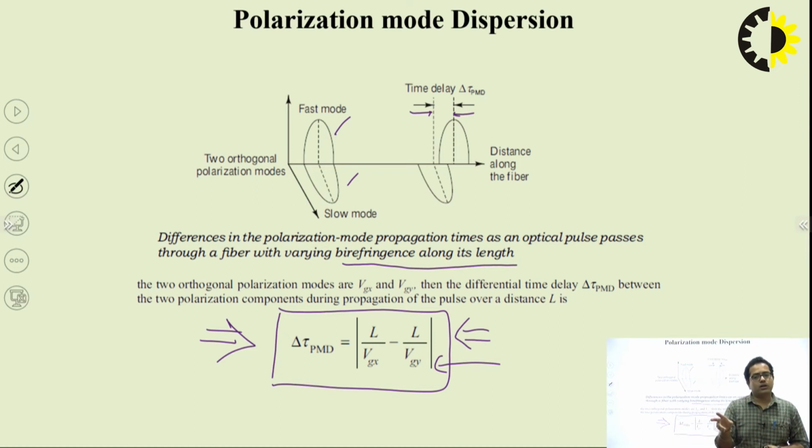And if your optical signal, or optical wavelength, or frequency, a better word is frequency, is striking the molecules, and this frequency matches the resonance frequency of that molecule, silicon dioxide, that leads to the absorption of the optical signal. If optical signals are absorbed, there is no way to get that signal back. It's totally lost. Whereas the other way of losing it is called radiation, radiative modes.